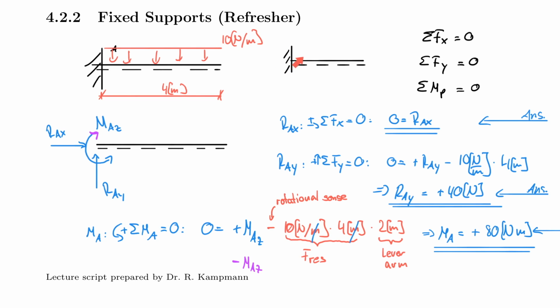So this clamps this beam, and because it clamps, you don't just have the vertical and the horizontal force, you also have the rotational force. That guarantees that all these 3 equations can be satisfied by just one support reaction. And that gets us ready for our examples, and we can now go ahead and solve cantilever problems with distributed forces on them.